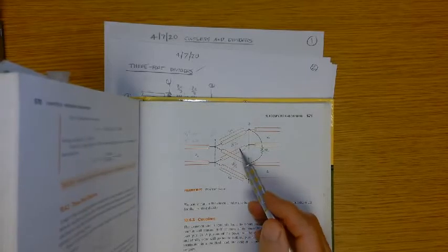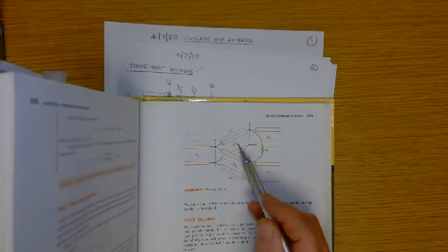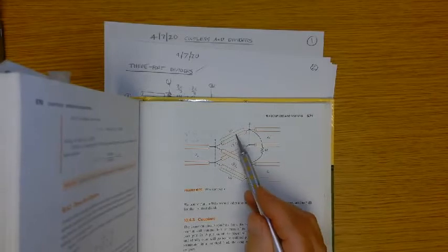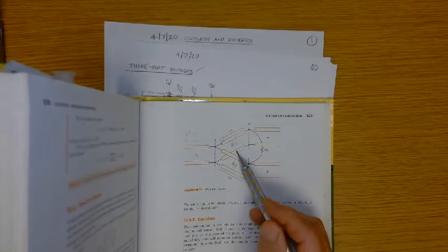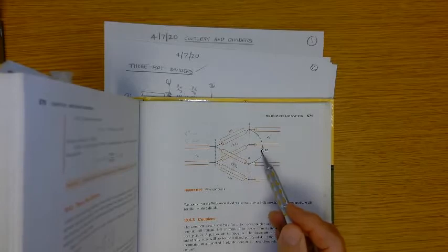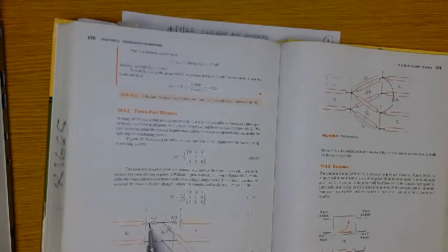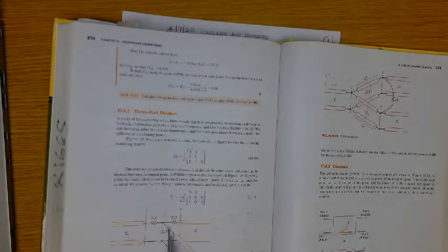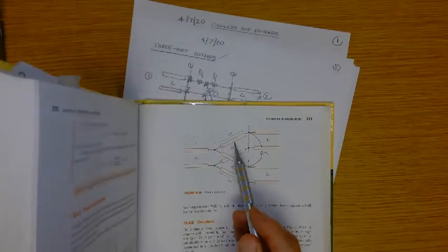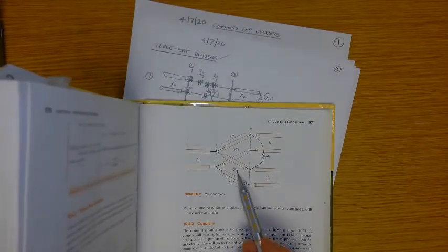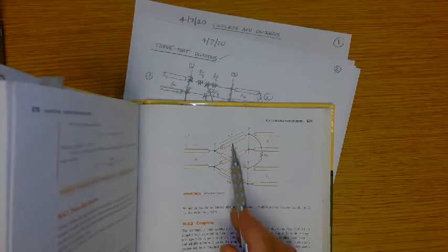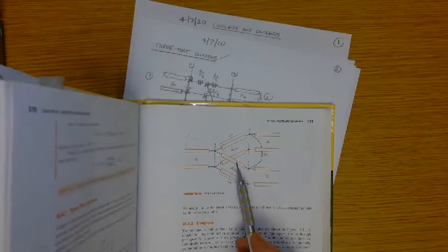What's the difference between a characteristic impedance and a regular impedance? Well, characteristic impedance is the voltage traveling wave divided by the current traveling wave. This impedance is a power loss type impedance. Similarly here. So you're propagating through, you're dividing by virtue of a power loss. Here you're dividing, at least to some degree, by a lossless device, just the T line itself.